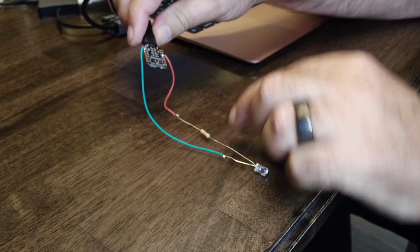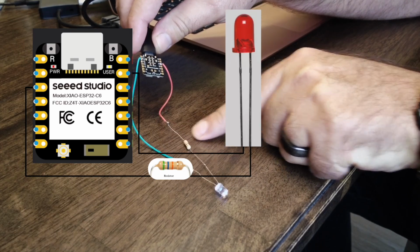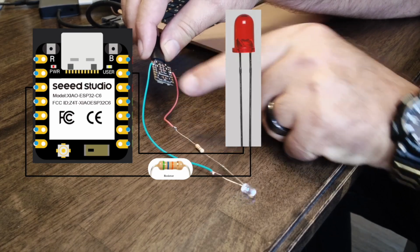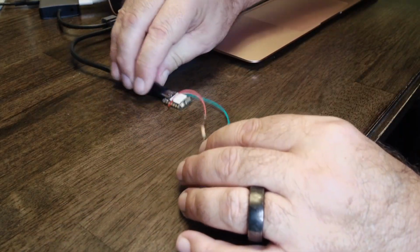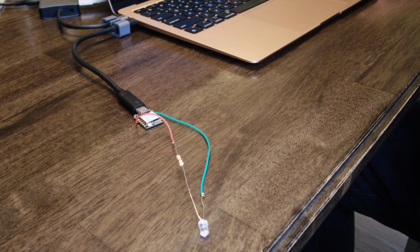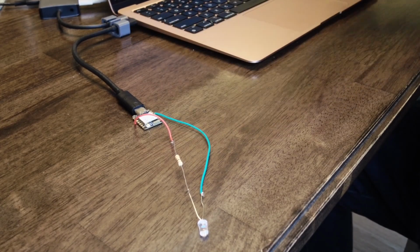We've got the red wire of the long leg of the LED connected via a 330 ohm resistor to D2, and we've got the other side of the LED connected to ground. You can use any microcontroller. I'm using this Seeed ESP32C3 because it has built-in Wi-Fi and it's small. I mean, to see how small that thing is, it's crazy.